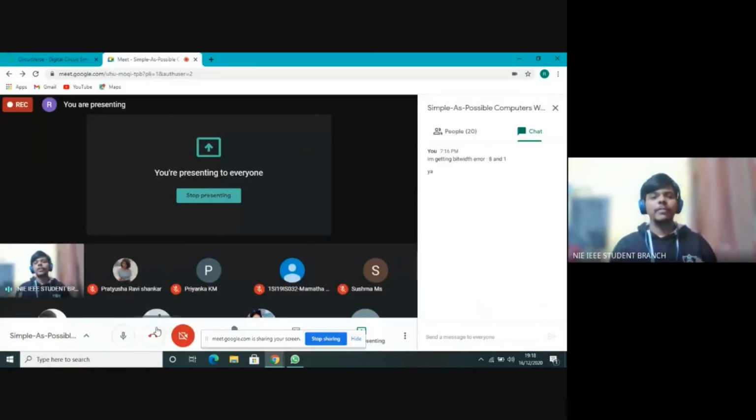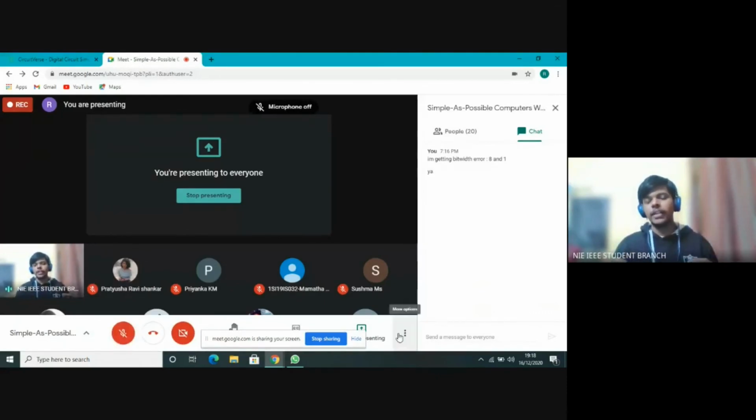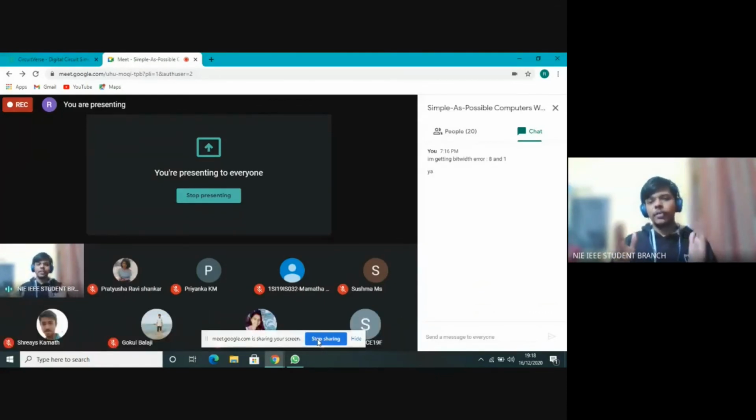Also, another quick tip: when you're doing the splitting, first it'll prompt you for the number of bits, the bit width. Say you give 8, and then it'll ask you how you want to split it. You separate the values with a space. If I have 8 and I want to split into 4 and 4, in the second dialog box that shows up you give 4 space 4. Then it will split it into 2 groups of 4.